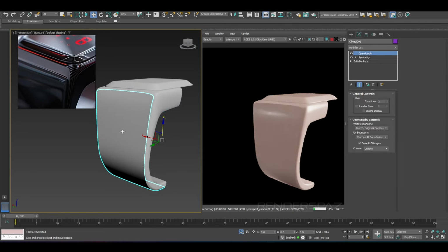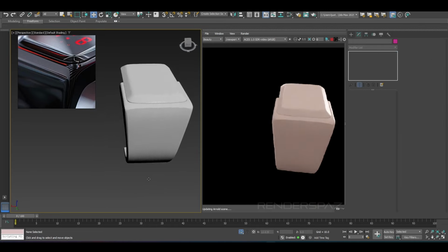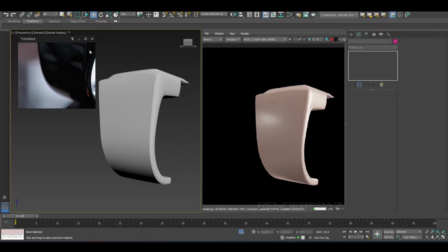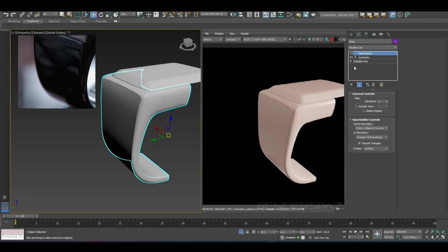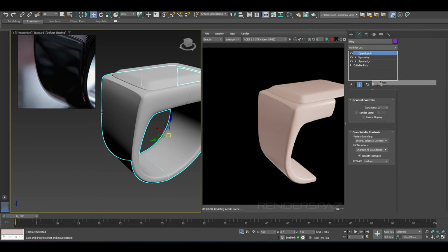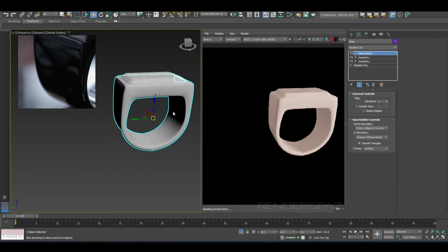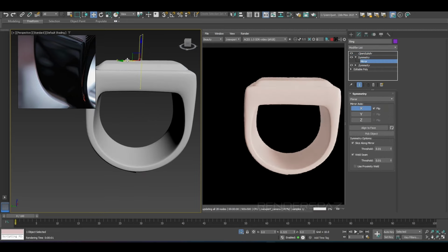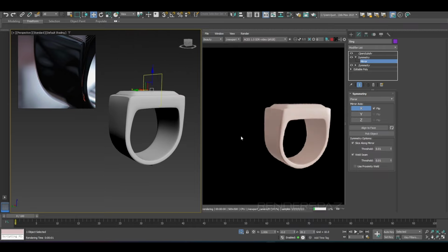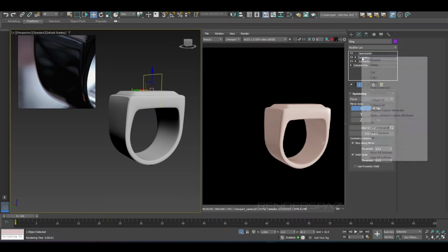So now we're just going to paste our stack here with the open subdivisions and symmetry. And now that should all work on the other side once we, let's see here, copy and paste it in there. Okay, we got a little bit of a gap, not a problem. Just bring it inwards a little bit. Make sure you're at 0 in Y. That should seam together nicely.